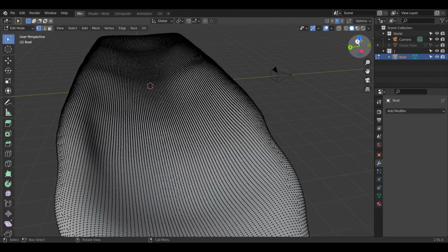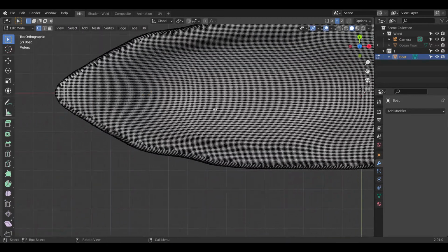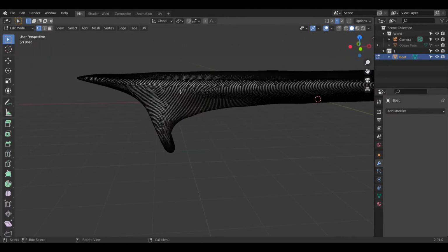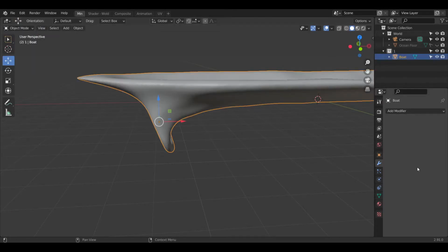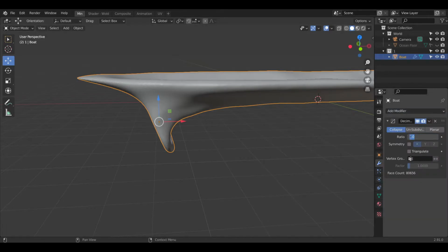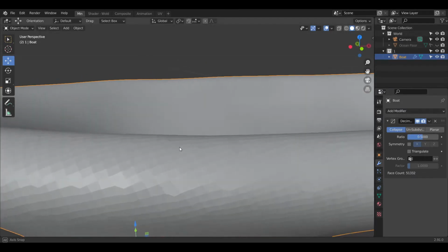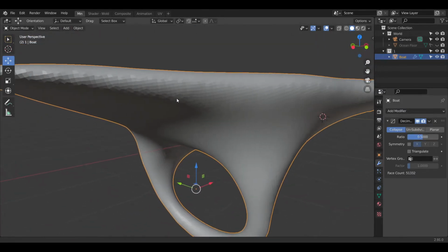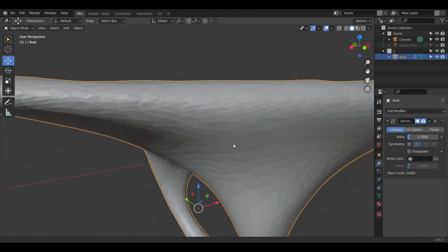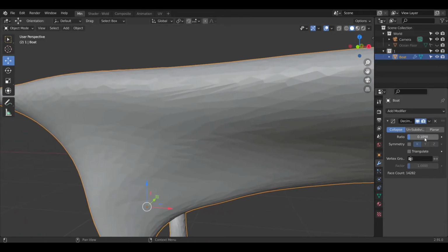So here's the idea. I'm gonna go up top of this thing. It's actually still really dense. Why is it so dense? Let's decimate it some more. Where are we at? Decimate. That should be roughly the same as what we had before. So let's do 0.3. Let's really get this thing small. What happens if we start going really, really small on this thing? 0.05.